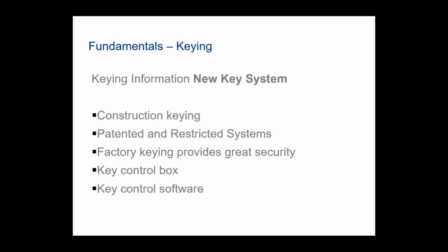If that keying is going to be protected, whether it be for 10, 20, 30 years, or if it's restricted, where no one else can get that key, you have to keep in mind, if they're patented, if they're restricted, you will have to really think about locksmith's access and also local access to that keyway if you have a problem, if you need the building rekeyed or something along those lines. Because once it's restricted, you're going to have a hard time unless you have a letter of authorization and that sort of thing to get that facility rekeyed.